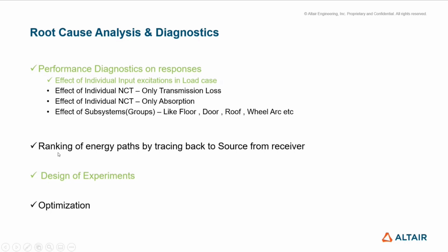So we are working on a way to identify the source energy paths in ascending order, to identify which is the major path from one particular source. You can have multiple paths to the receiver, just like a transfer path analysis in low frequency. So we are coming up with a workflow where you can identify the overall path which transfers most of the energy.